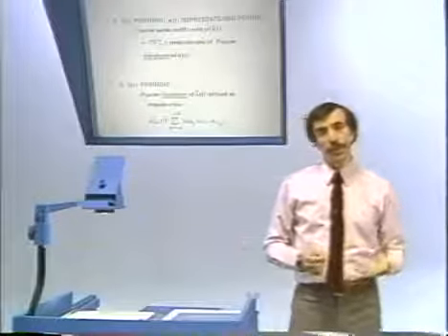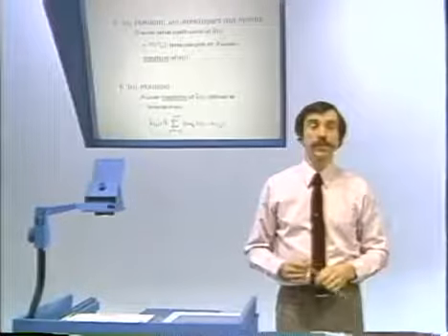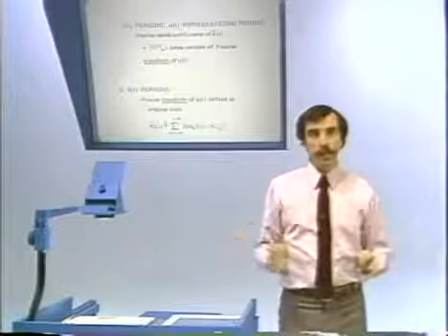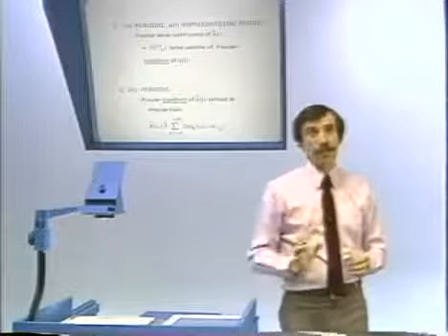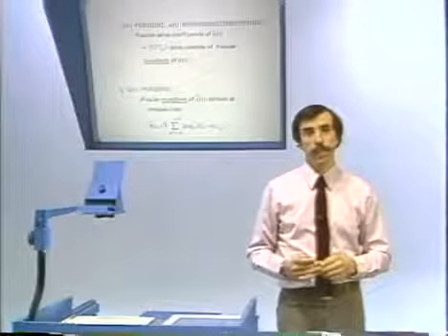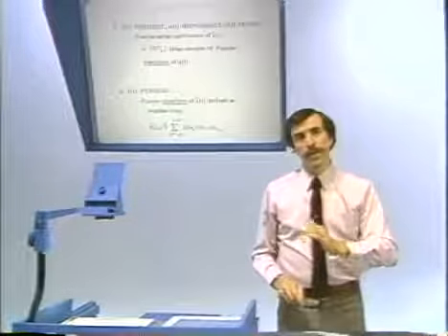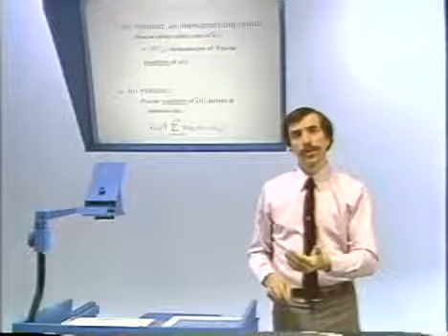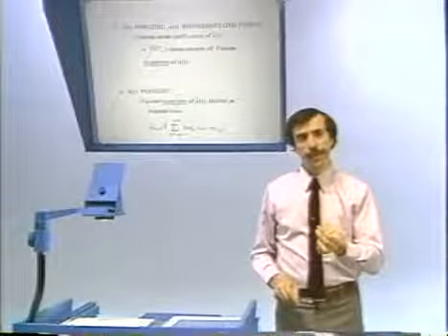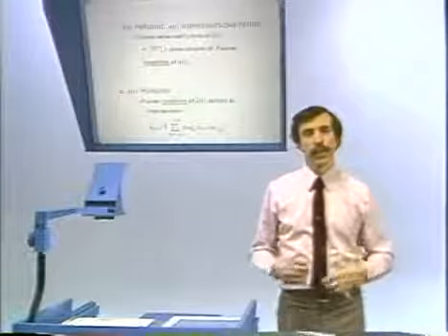What I pointed out at that time was that if we define, and take it as a definition, the Fourier transform of the periodic signal as an impulse train where the amplitudes of the impulses are proportional to the Fourier series coefficients, and we plug that impulse train representation into the Fourier transform synthesis equation, what we end up with is the Fourier series synthesis equation.